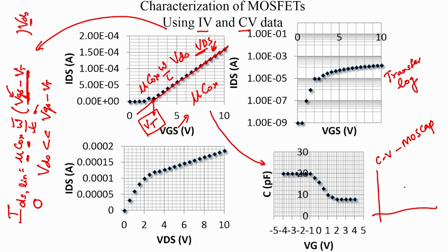Okay. So, we have the capacitance and voltage curve, and what we have done is we first performed a low frequency measurement and we obtained characteristics that looks like this. So, let us say we performed another measurement, but it is at a higher frequency, and at some point let us say when the frequency was say 1 megahertz, we obtained the high frequency characteristics of a MOS capacitor.